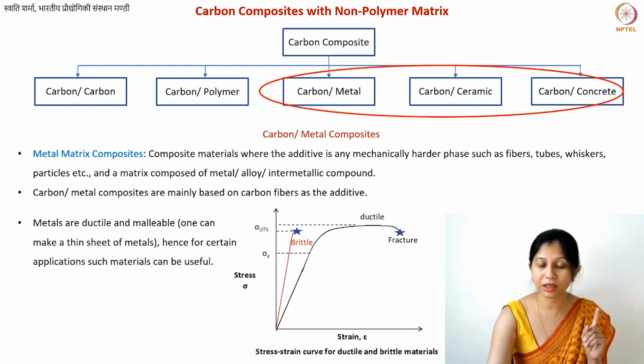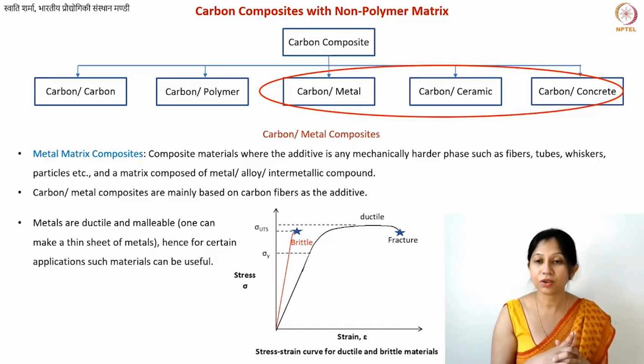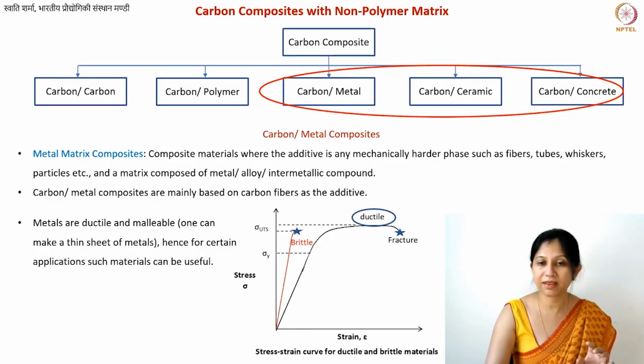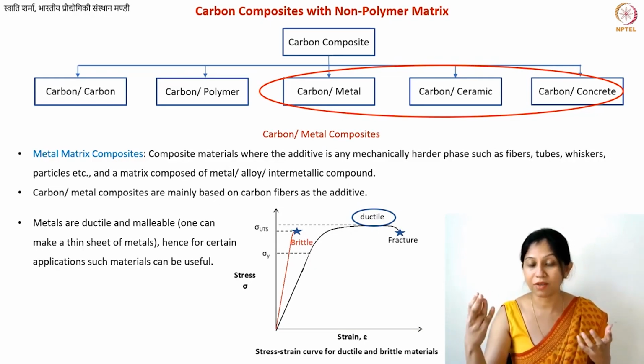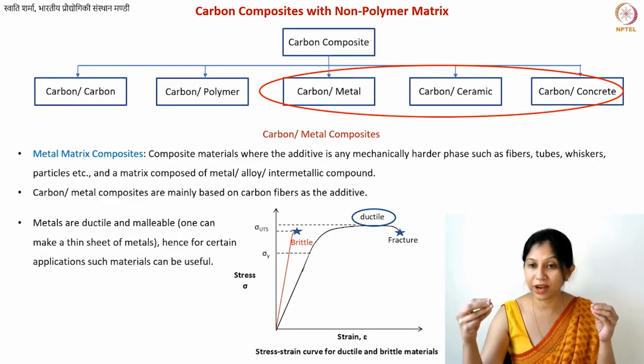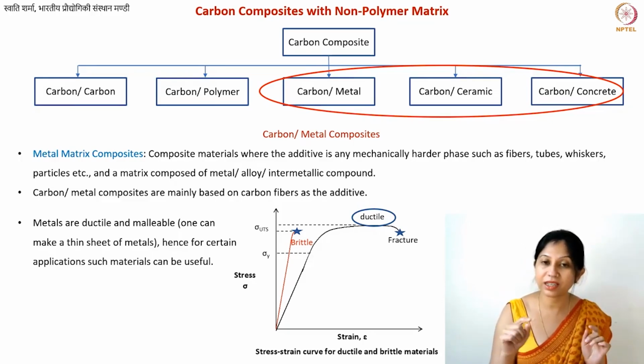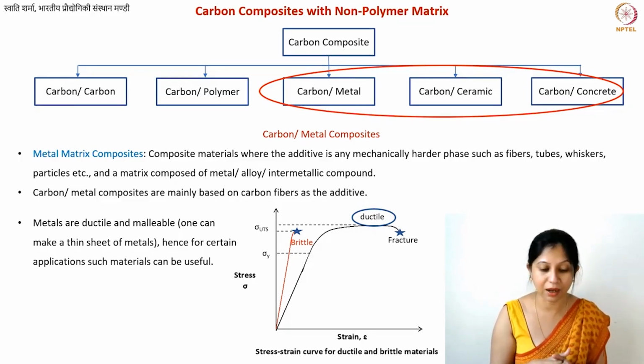Now we had also learned about this ductility property before in one of our previous lectures. You can see in the stress strain curve, this is your region before the fracture, after the material stops behaving as an elastic material, and then you have a certain region of strain, and then you have the fracture. So this region is known as ductile behavior.